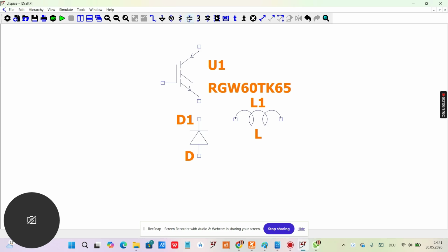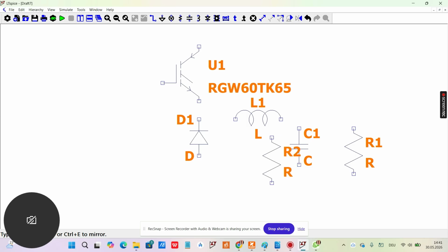And next I need a capacitor to place at the output that will help to smoothen the voltage that will be outputted. So next I'll click here. Capacitor is placed. I press my escape button. Next I choose the resistor. I put it in parallel. This is my resistor, it is like the load, which I want to view the output. So I'll click escape and it goes away.